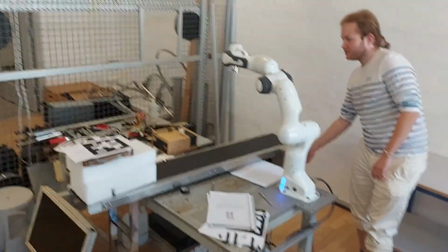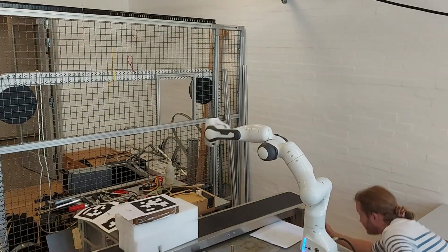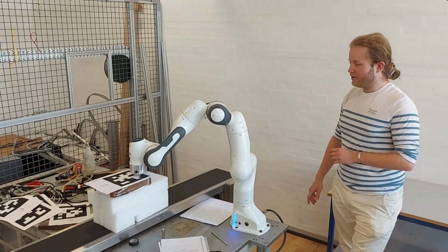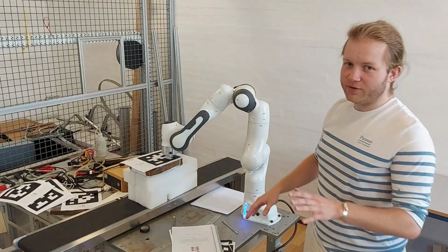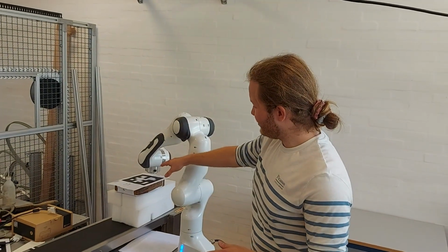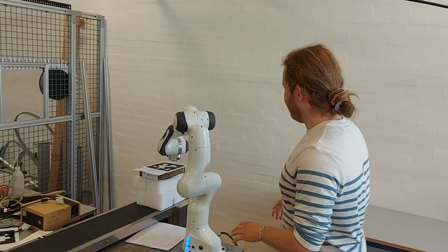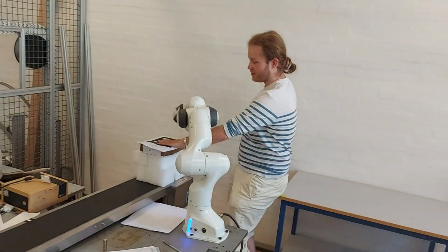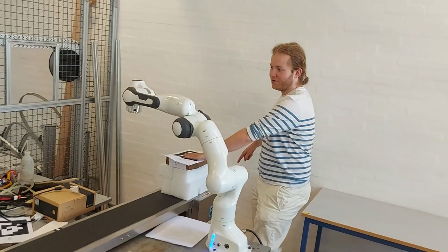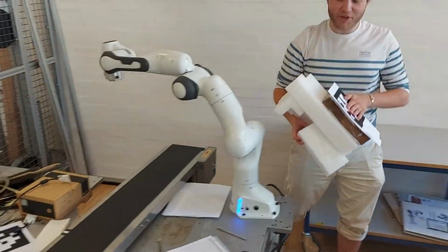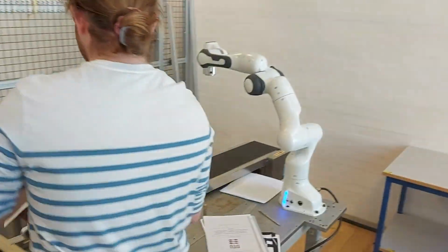The conveyor belt is set to 2 right now. The Kalman filter's main purpose is to prevent the robot arm obscuring the target from stopping the robot arm, and we can see that the robot arm is tracking the object roughly. We can see that the robot arm continues because it thinks the velocity is making it go in that direction. And now when the predicted position went outside of the reach zone of the robot arm, it went back to its waiting position.